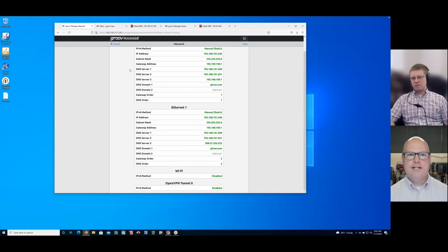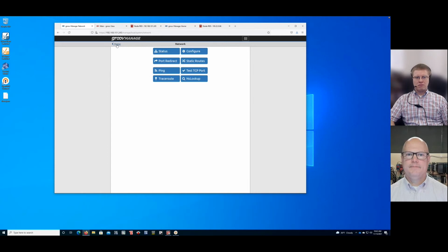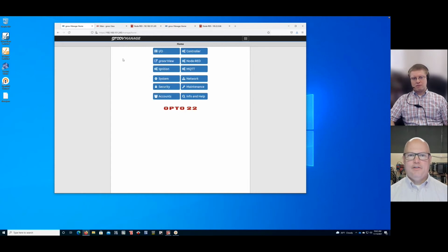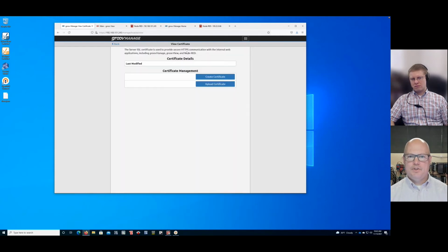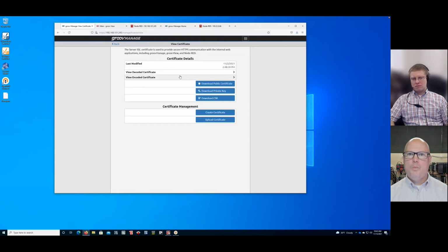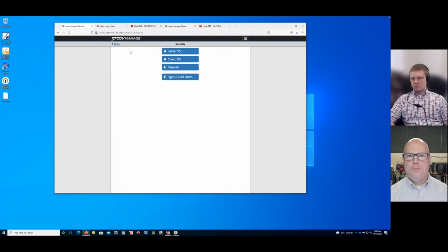Oh, yeah, and that's where it all gets configured. So great question. It was actually what we were going to talk about next. And then, of course, whenever you realize, well, wait a second, if I can open up ports and expose it, what kind of security exists on the EPIC controller? And, well, that's a great question. So on the controller itself, there's a server-side certificate that you can use. It does come with one, or you can set up your own, and use a fully qualified domain name.